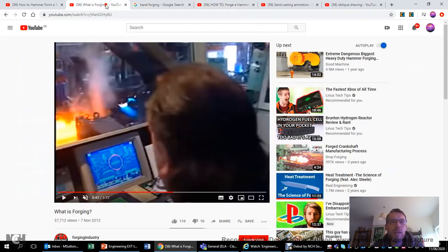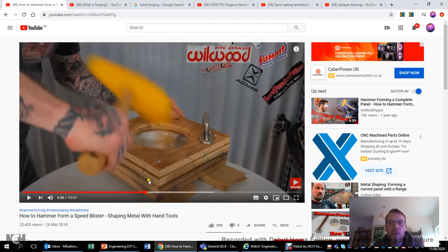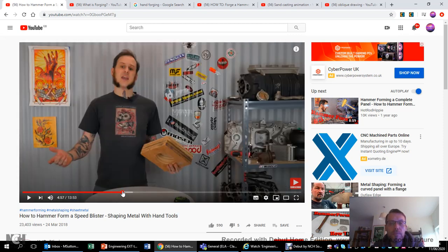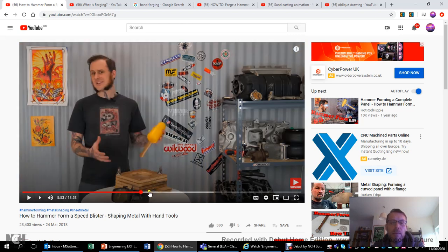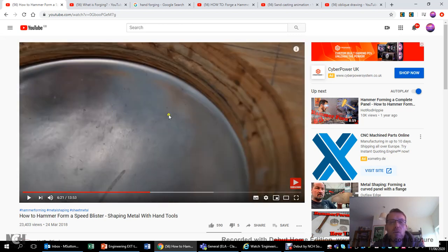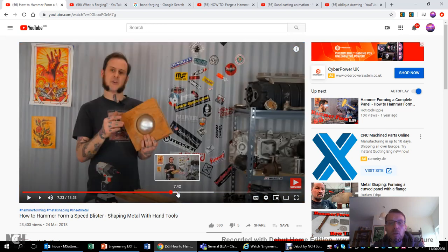Those videos, by the way, are on how to do hammer forging. This guy here is doing cold forging. I will place this one in. He uses it, and you can see there's a mould just here. It's for making a dome, of all things, and it's clamped in, and he's using this hammer action, and that can also be used to hammer out softer materials. Things like aluminium allow you to do this, and that allows you to make a dome, because you're stretching the metal by hammering it repeatedly, and that can form the dome.